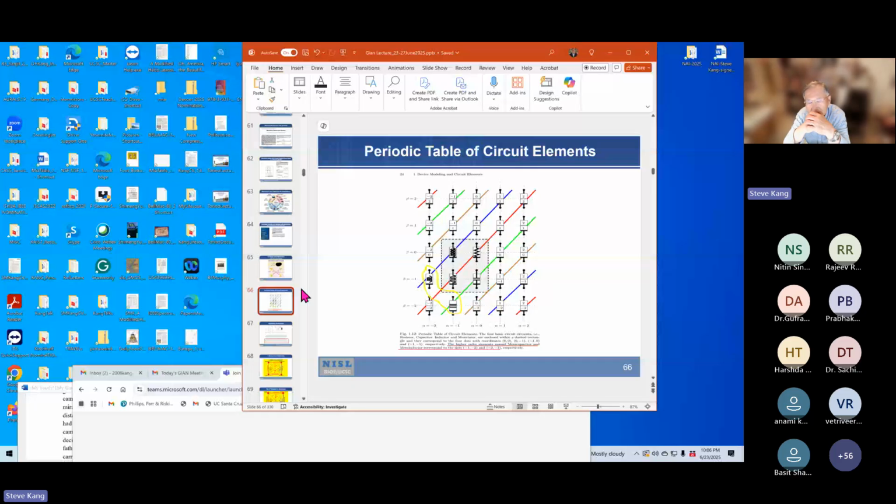One of the key components of the memristor in neuromorphic computing is the MAC operation, multiply-accumulate operation, which we will discuss when we get to neuromorphic computing. That is huge. There is lots of matrix multiplication, but using a memristor crossbar array, you can have a very energy-efficient analog computation. To me, that's a huge advantage of using a memristor array.